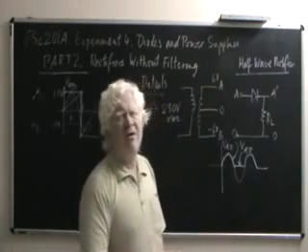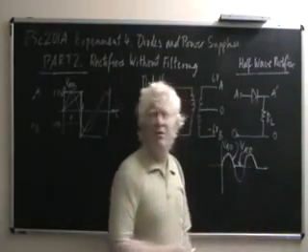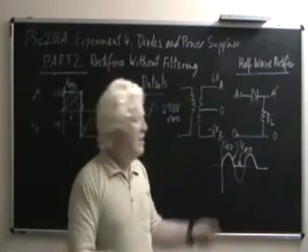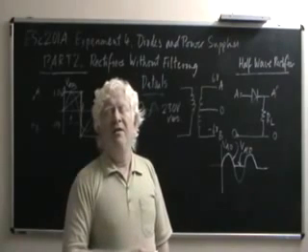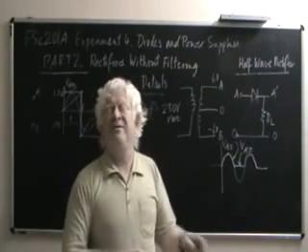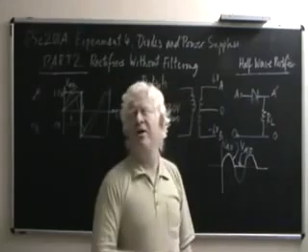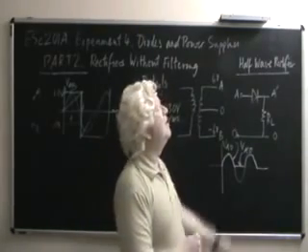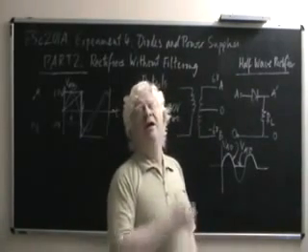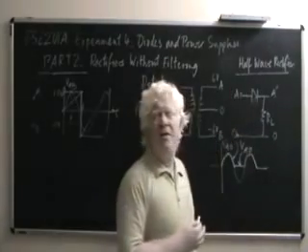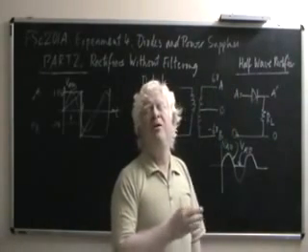One might argue that this half-wave rectifier is not a very clever thing, because while something is happening in the positive cycles, the circuit is just idling in the other half. That is valid, but this is not to say that power is being wasted in any way, because you see, the resistor carries no current in the negative half cycle, and it carries the current only in the positive half cycle. So if you measure the power consumed by the resistor, it is, assuming the diode to be ideal, equal to the power being supplied from this side. No power is being wasted.